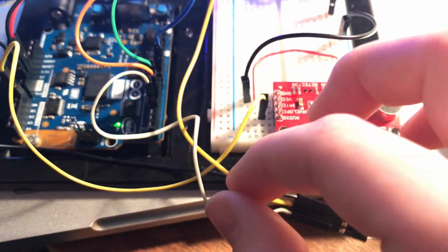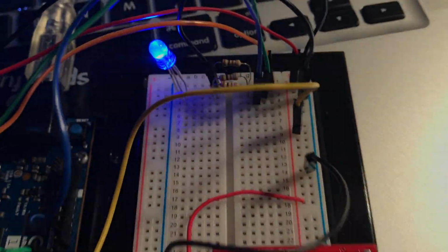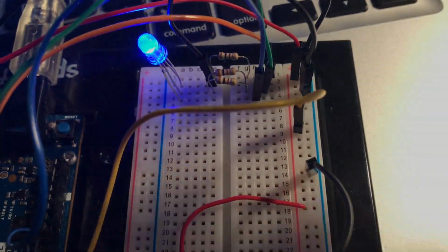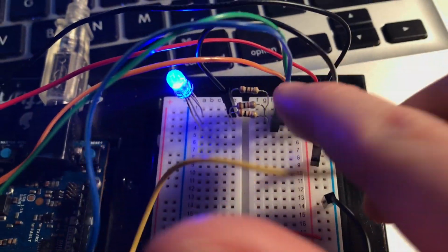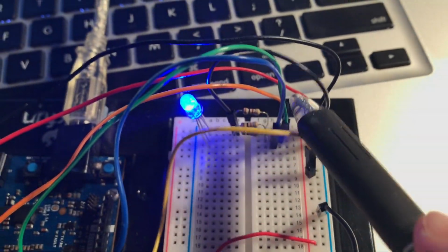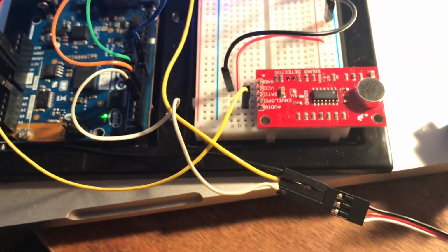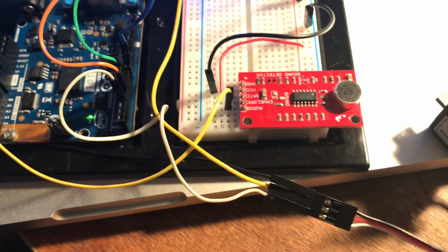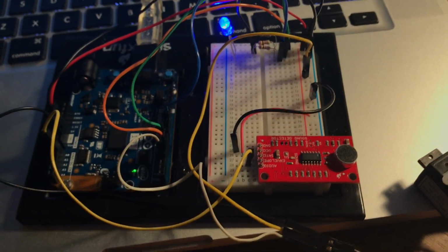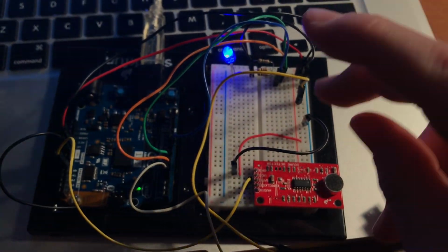It is connected to 5.5 volts through this yellow wire, which is connected to the positive column here, which is also connected to the red wire here that connected the sound detector board as well to the 5.5 volts on the board. And then it is grounded by the black wire here, connecting it to the ground pin on the Arduino board. So right now we can see that it is on case 0,